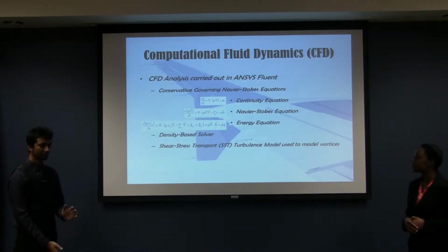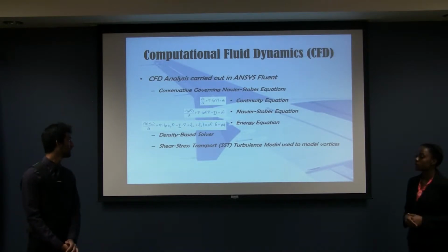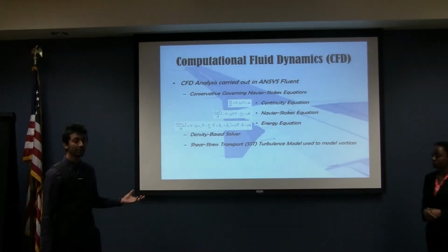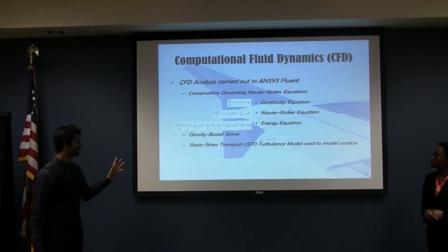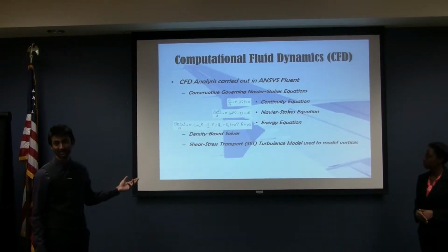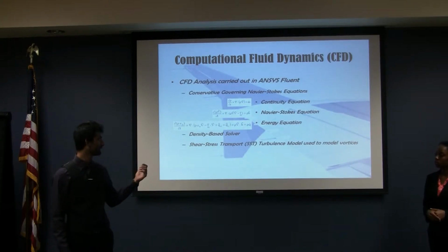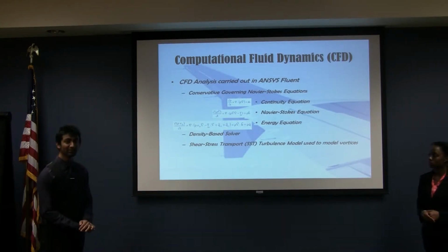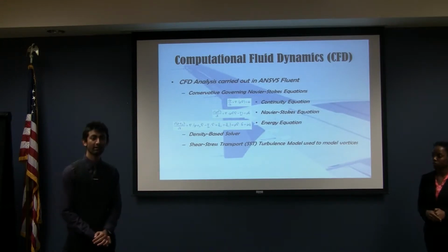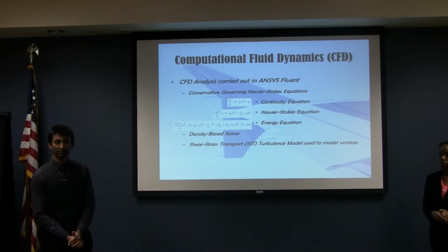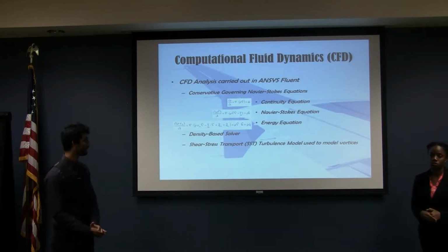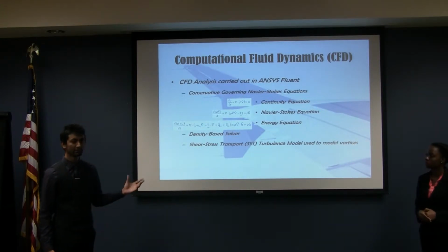Okay, now computational fluid dynamics, CFD for short. We'll be using ANSYS Fluent. ANSYS is a finite volume solver which actually has three equations integrated: the continuity equation, the Navier-Stokes momentum equation, and the energy equation. We'll be using a density-based solver because we are operating at a very high Mach number of 0.8, so we are expecting shock waves, actually compressible flows. So a density-based iteration scheme actually takes this into account.